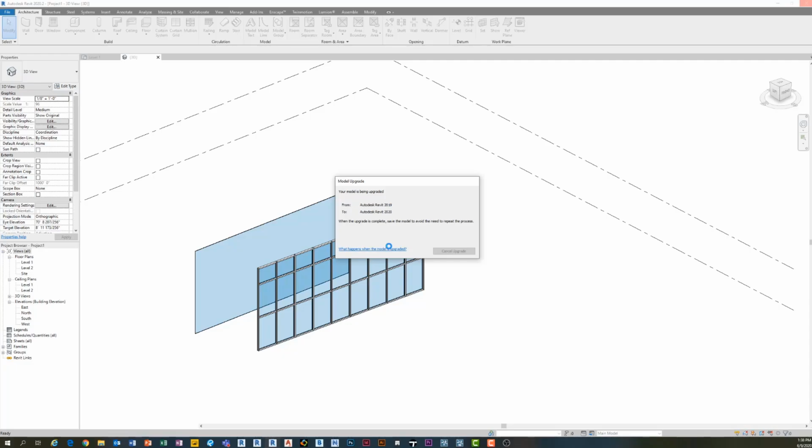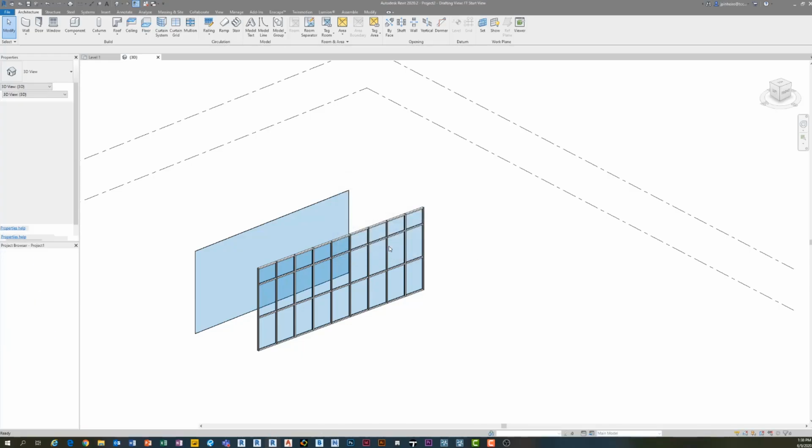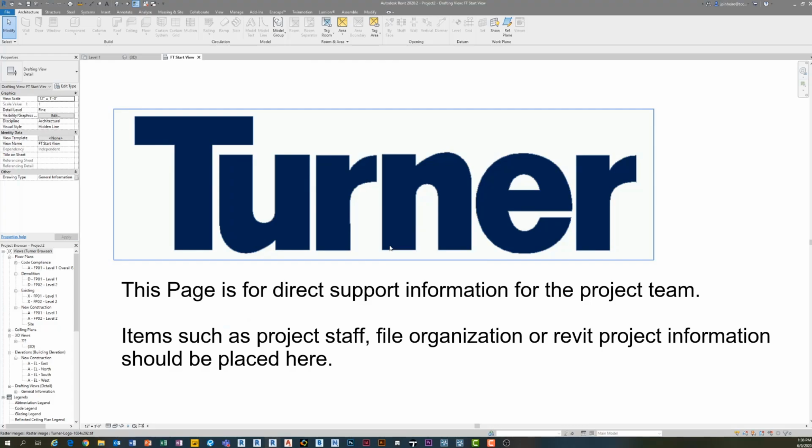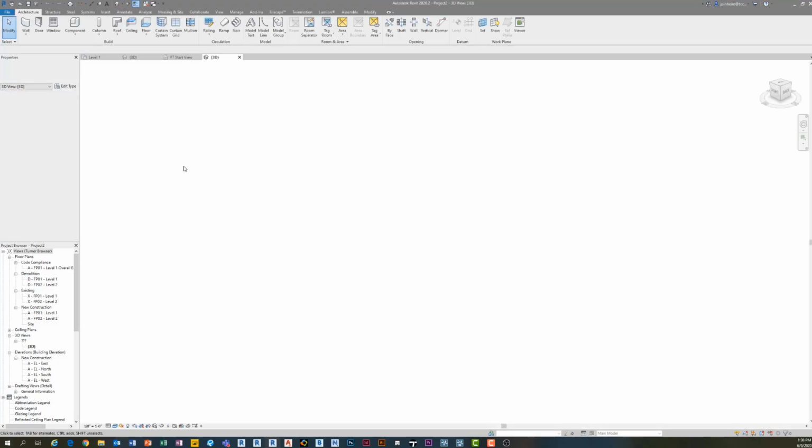But the reality is, what I've found is with curtain walls, you want to build into the system only things that make sense. So usually my curtain walls will have vertical spacing set up. They'll have usually mullions, at least mullion types applied, and a major curtain panel applied. But very rarely, unless you have a building where it's going to be a grid system, am I using a horizontal and a vertical system? And the reason being is exactly what you just said, Jerry.